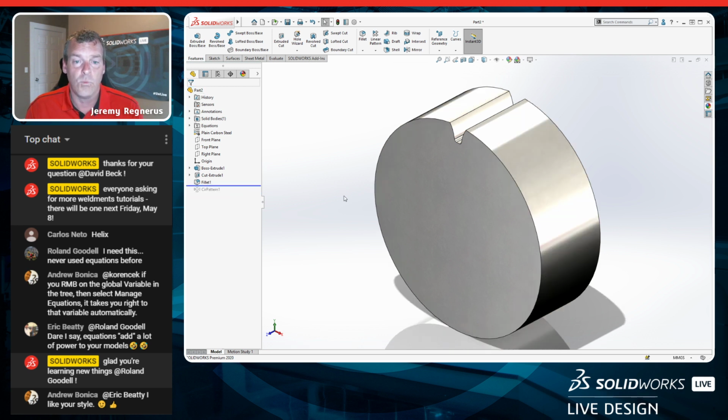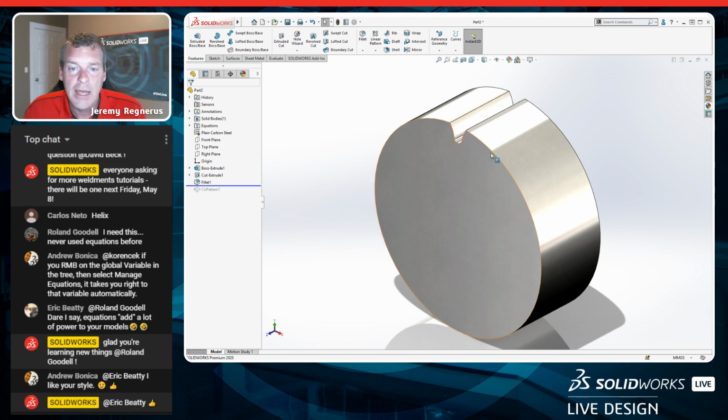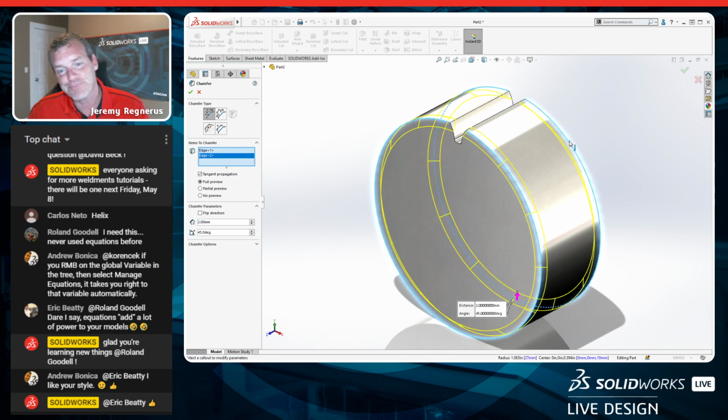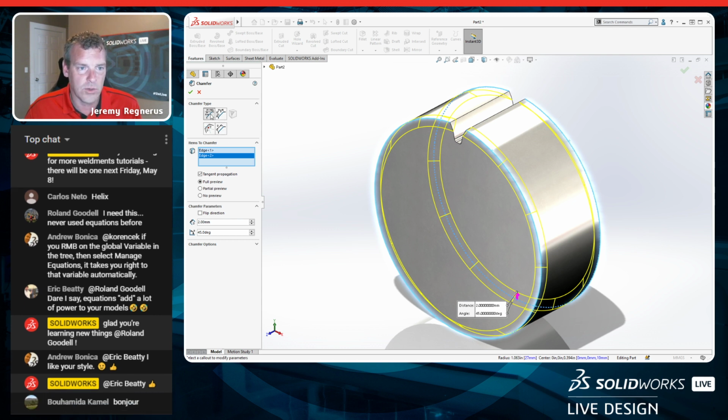Notice what we can do here. We can say, before we create that circular pattern, I'm going to roll back in the tree, grabbing that rollback bar, and we're going to add our chamfer now. I told you it wasn't going to be the circular pattern that we were going to create next. We're going to break these. We're just going to use a simple 45-degree cut that is equal to the module value, which is half of the tooth height. So I'm going to go ahead and we're going to do a distance, and we're going to make this a symmetric chamfer.